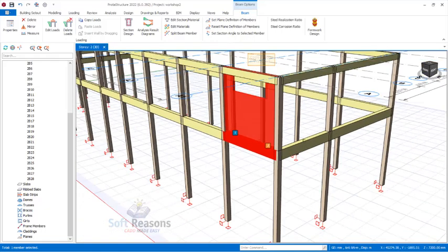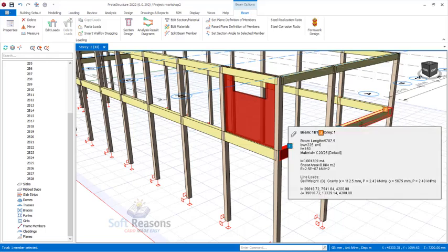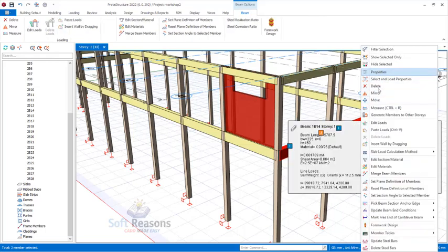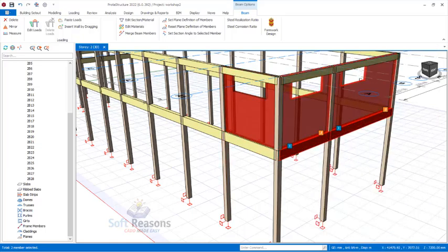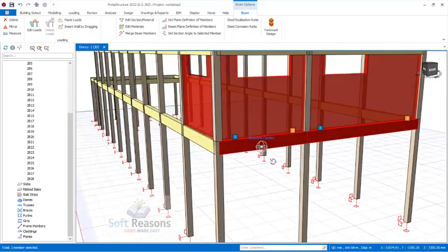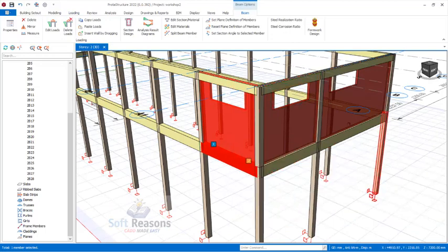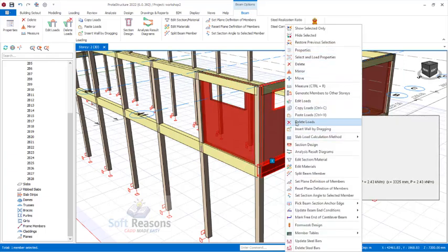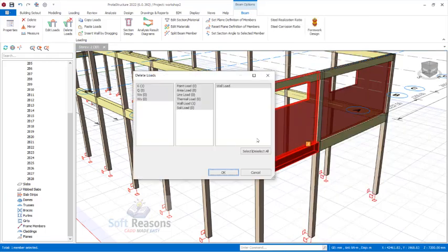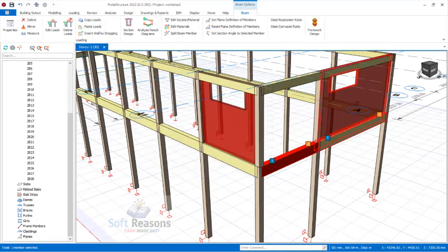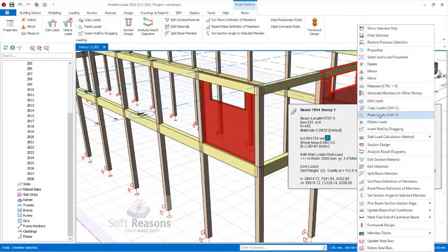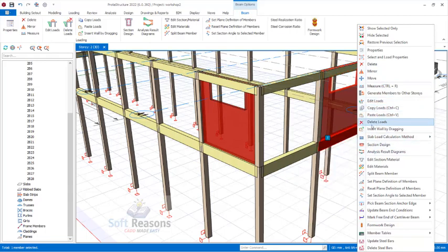So you can now select this, and then you can select it as well, and right click. When you say paste, right here, this has been pasted successfully. So if you want to get rid of the openings right here, right when we copied it, you can as well get rid of it. So over here we wouldn't have these openings. All right, so to delete it, you just have to use this option or delete load. So you click on OK to get rid of that. Then delete load. This is for the sake of learning, to get rid of that.